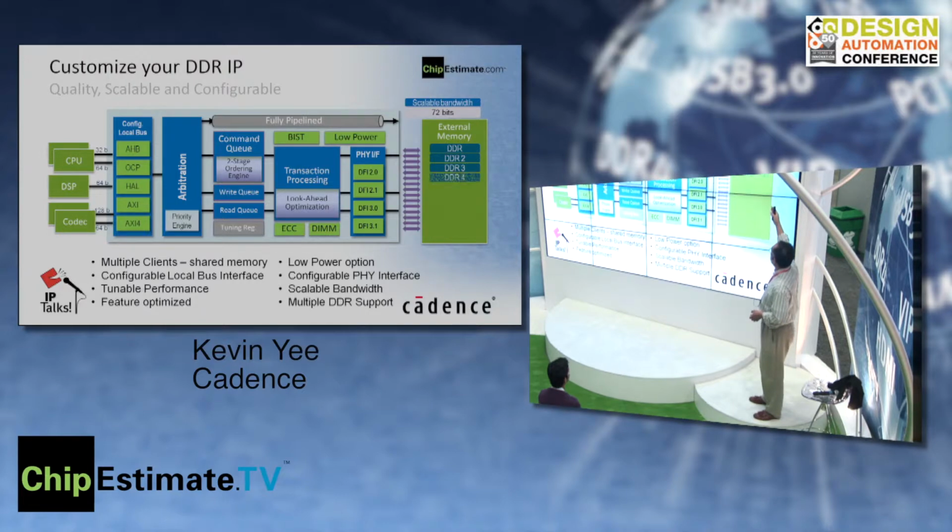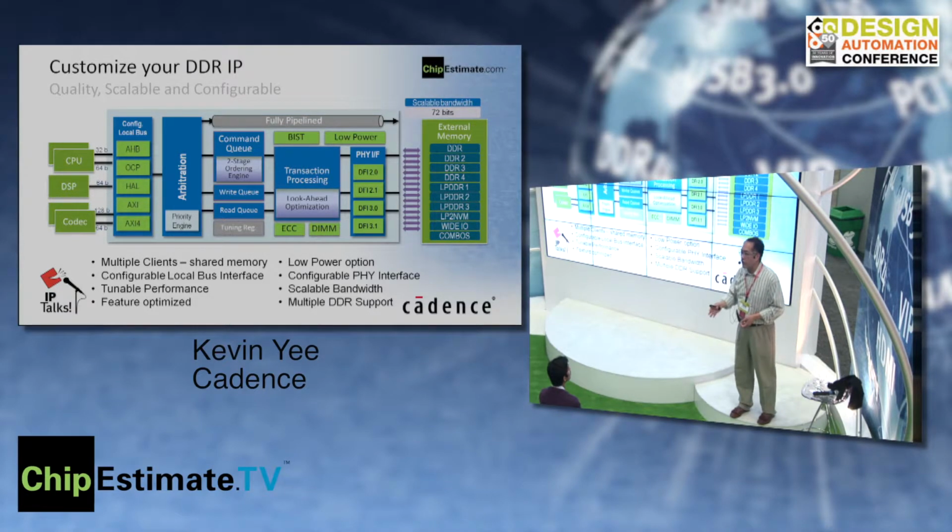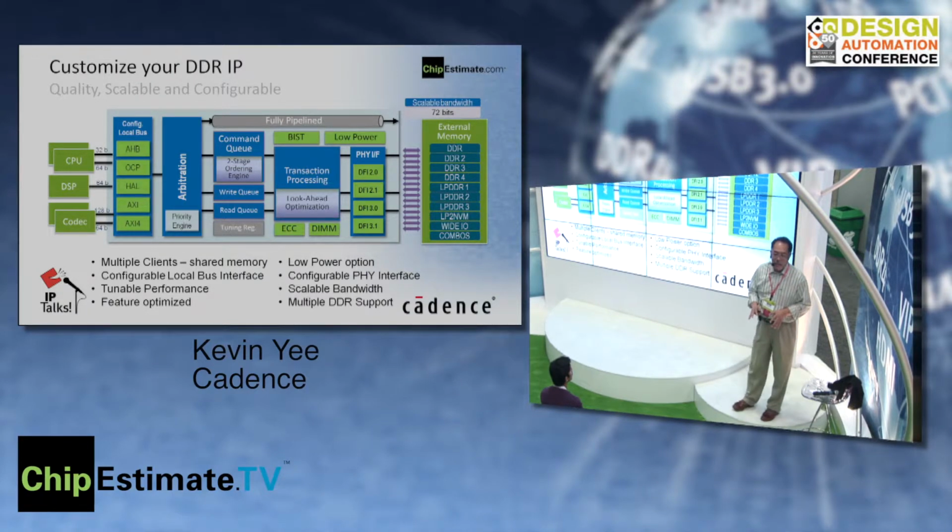More importantly, we will support multiple memories. And the nice thing about it is most everyone who uses our controllers wants support for multiple memories. It's not just about having support for DDR3 or having support for LPDDR2. A lot of times we'll do a combination of supporting DDR3, DDR2, and LPDDR2. So it gives you options in your designs that, depending on what the memory prices are, within your system you can change out that memory, because you have that controller that will support it all. Or you want the latest, DDR4, DDR3, and LPDDR3. So we will support those configurations for your SoCs to give you a lot more flexibility at a system level, not just at an IP level. And really, it's all about what the system looks like. It's not about the IP. So we're trying to give you as much flexibility within your SoC design.